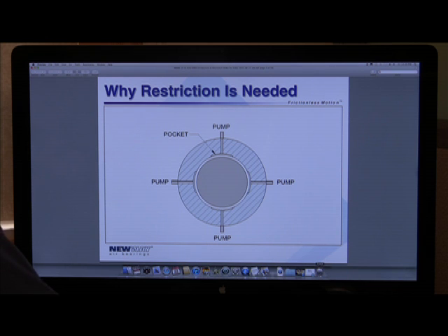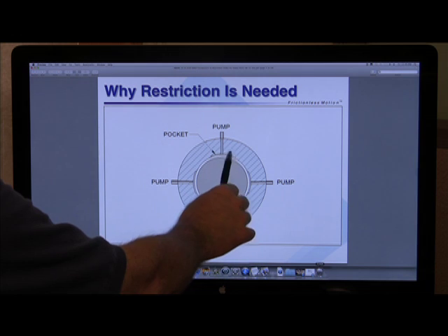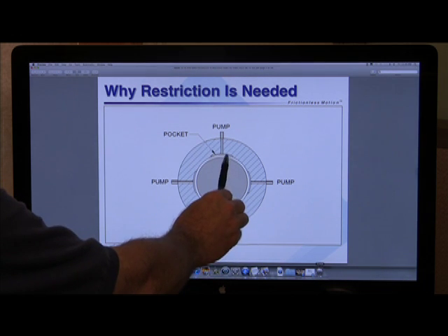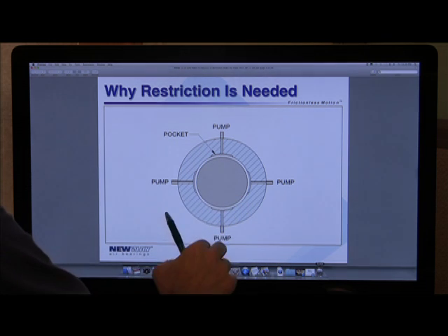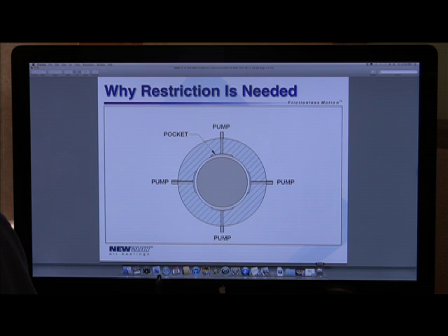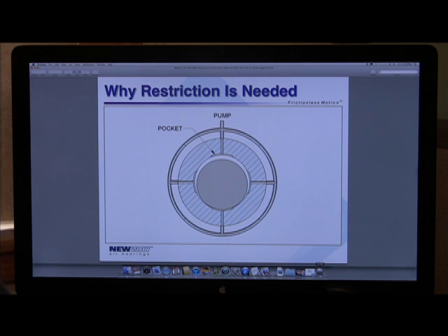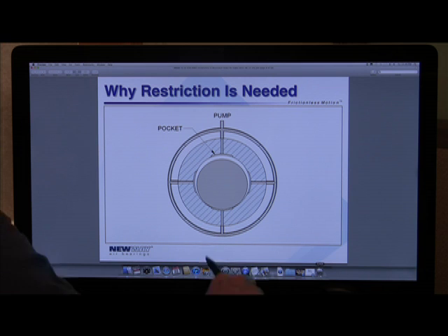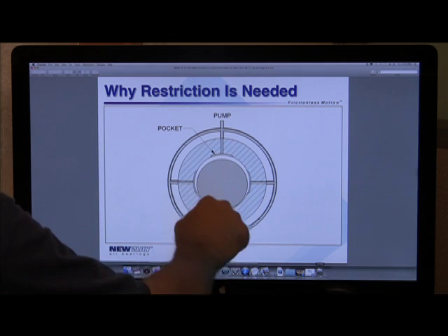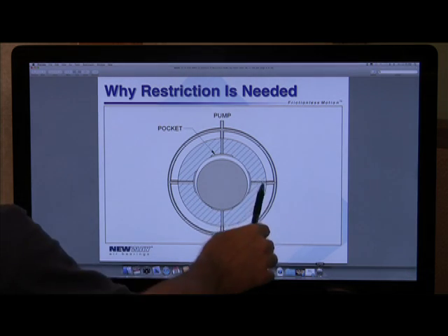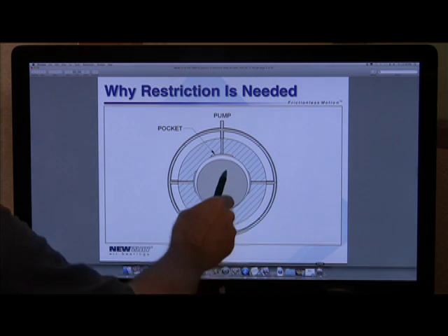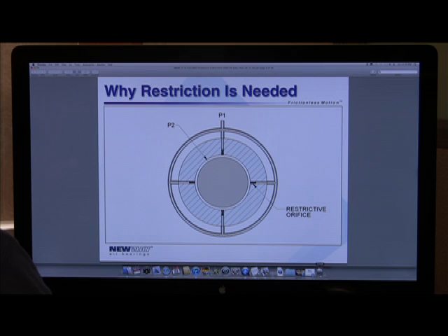Now, in hydrostatic systems using oil or water, sometimes you'll see pockets used. The advantage there is you can get the exact same pressure across the whole pocket. The problem with air is that it's compressible, so when you have thick layers of it, it loses stiffness and it becomes subject to pneumatic hammer. But with oil and water, you can actually increase the amount of average pressure in the gap. Again, if you've got pockets, which is basically trying to separate this annular groove, unless you've got restriction somewhere else, you're still going to be defeated because all the air is just going to come out the one bigger gap.